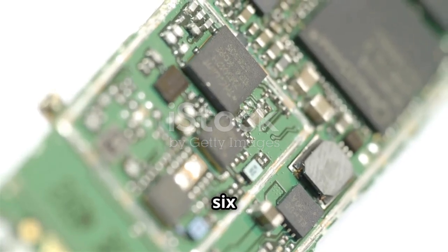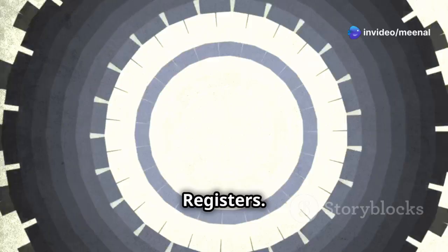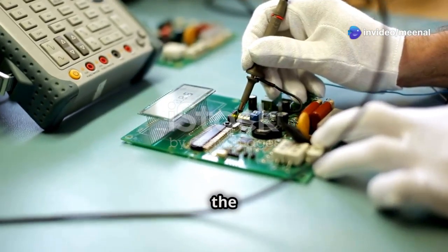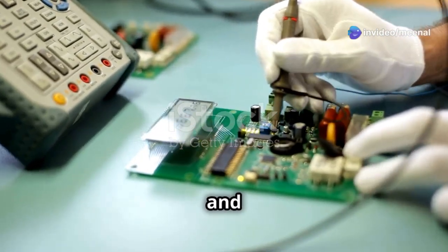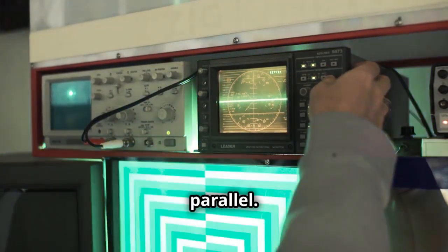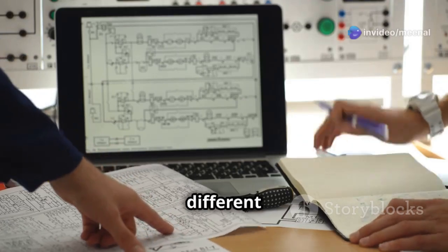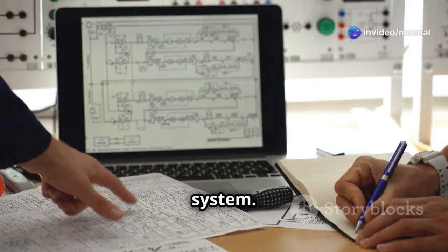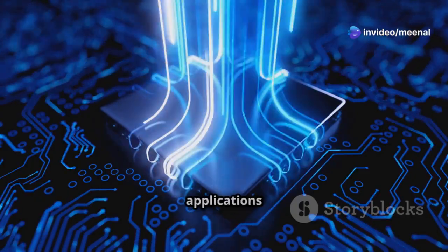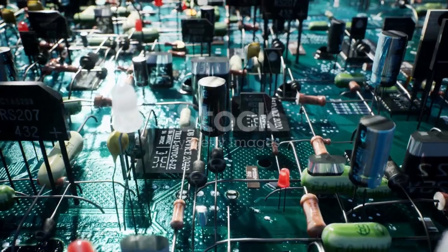Section 6. Parallel in, parallel out, PIPO, shift registers. The PIPO shift register combines the capabilities of parallel input and parallel output. Both data loading and retrieval happen in parallel. This configuration allows for the simultaneous transfer of data between different parts of a digital system. PIPO shift registers are suitable for applications requiring high-speed data transfer and manipulation.